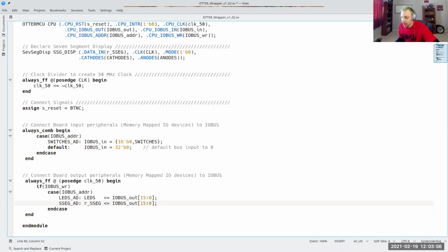What's the difference between these two pieces of hardware? The always comb is combinational, and the FF block uses sequential logic, uses a register. Yes. And so that is the difference, right? You always need a default if it is combinational logic, right? So many of you in 133 got drilled in to always have a default, always have an else, right? That is true if it's combinational, right?